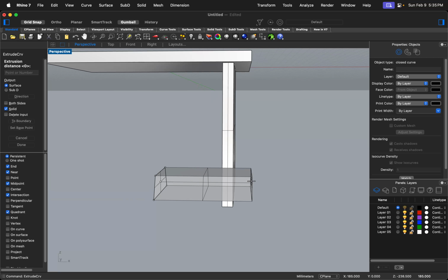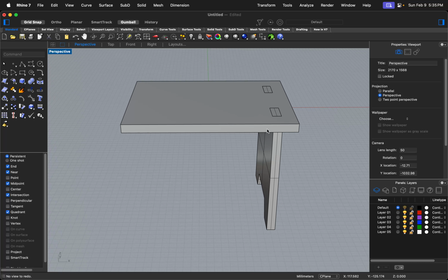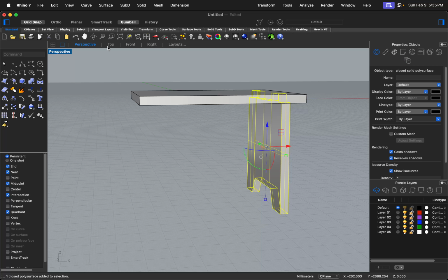And what I'm doing now is creating another cutter. So once I'm happy, I will pick up the leg, hold it, boolean difference, take the cutter, and we trim away the legs. And make a nice half cut at the bottom here. Once done, I can then take this one. Alright, so good. So next, before we do the mortise and tenon cut at the top here, which is the mortise on both ends, I will have to duplicate the legs first.